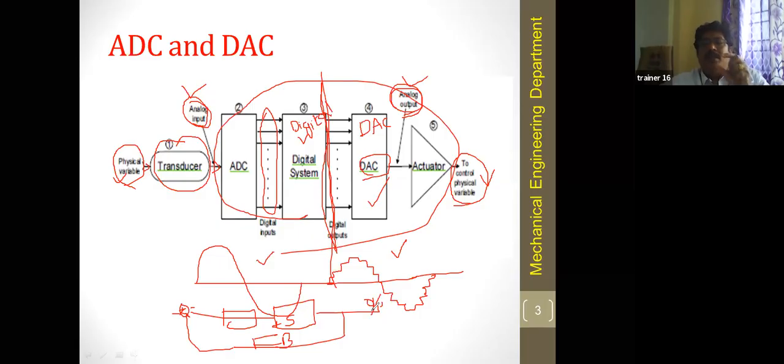For example, take the single acting cylinder and double acting cylinder. Here the piston is moving forward, right? I need the piston to move only, for example, 20 centimeters or, say, 25 centimeters. For that, the compressed air pressure should be correct.